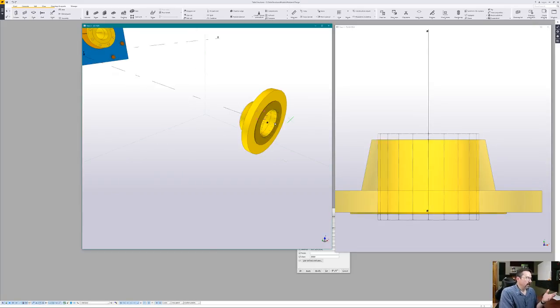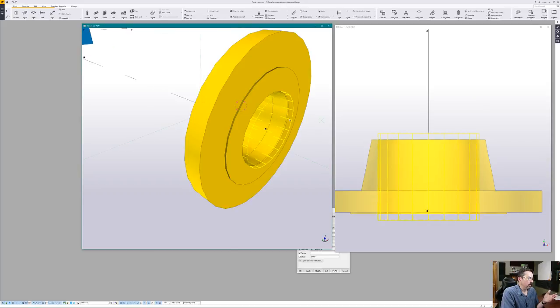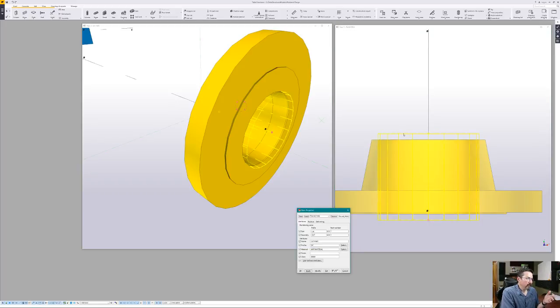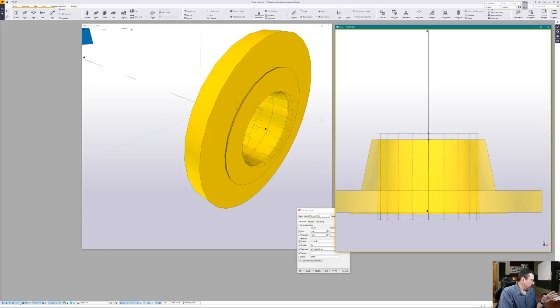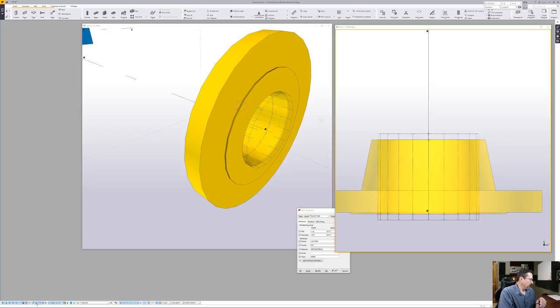And if you want to be able to select, you can see how I'm rolling over the cut here, and I'm able to actually select it. And if I double click on it, it brings up all those things that I had brought up before, or what I'd used to actually draw that with. If you want to be able to select those, down in your toolbar, down in here, it looks like a pair of scissors, and if you select those, it will allow you to select the cuts. If you have that turned on, you're not able to select the cuts, and sometimes you have to turn that off in order to delete the entities that you cut with, if that makes any sense.